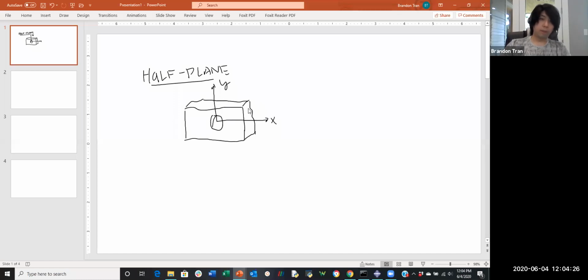So let's assume on this half plane that we're just applying a uniaxial load, we'll call it sigma 0. And obviously there needs to be an equivalent load on the back, or else there won't be stress in the system. So we're applying a uniaxial load, and we're going to use what is known as Airy's stress function. Airy's stress functions are clever little mathematical devices used to first assume the solution of the function and then prove it kinematically later.